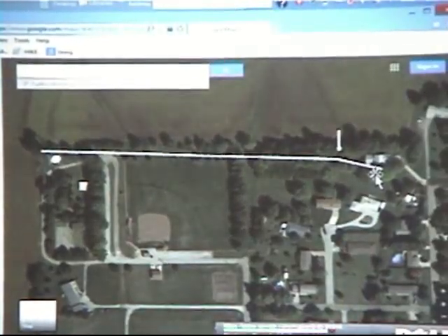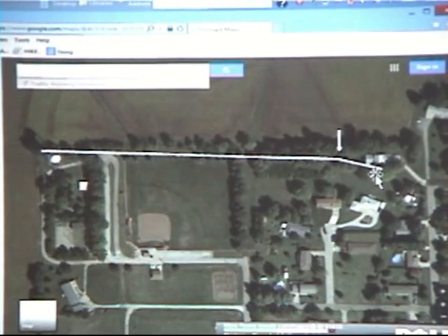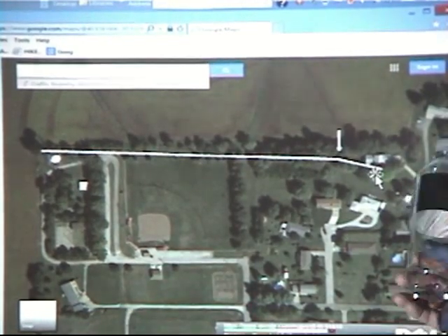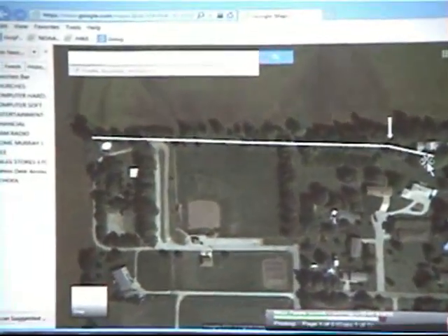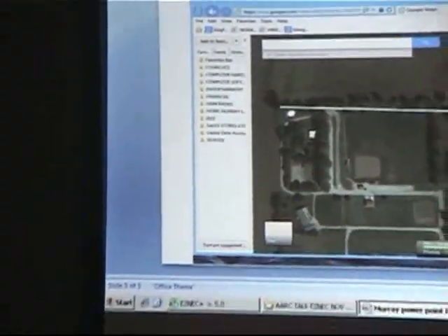So I had a 2 wavelength long wire and sort of end-fed. Not end-fed totally, but in. I fed it in a quarter because the impedance would be pretty close, I hoped, to what it would normally be. The tuner that I would use probably shouldn't have been too dramatically different. And it wasn't.